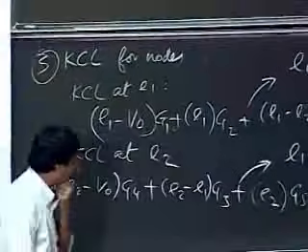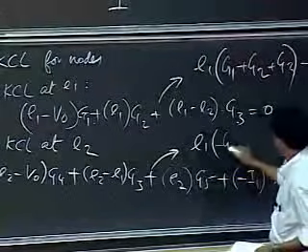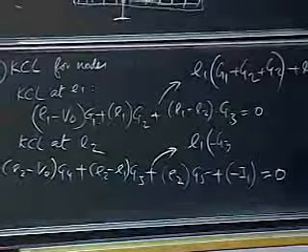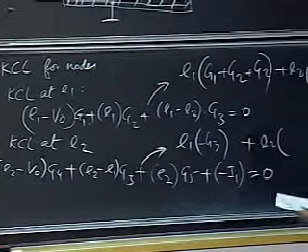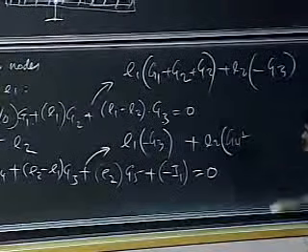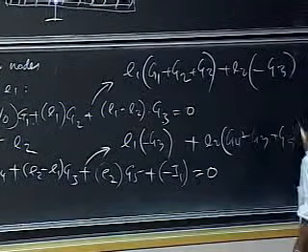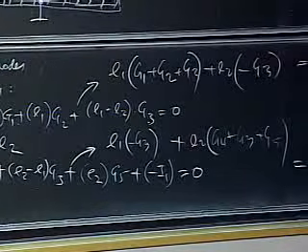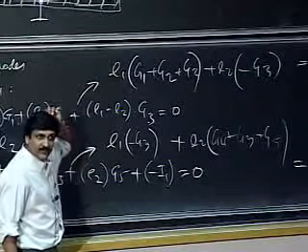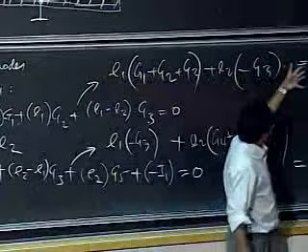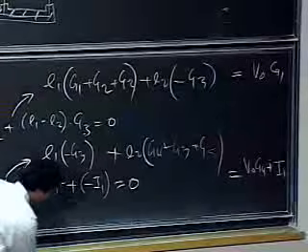So I move my voltages and currents to the other side. And let me collect all the coefficients for E1 here. So E1 is minus G3. And that's it, I guess. And then I do the same for E2. So I get G4, and I get G3, and I get G5. Okay? So notice here that I have two equations and two unknowns. On the right-hand side, I have some voltages and currents, which are my drive voltages and drive currents.